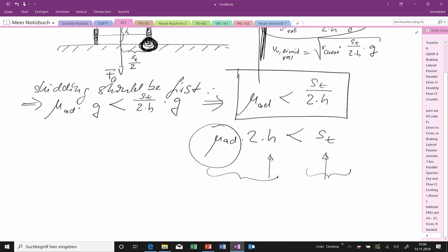So if we steer and we let the vehicle roll to one side, and then we steer in the opposite direction, and it rolls back to the other side, and if we do that excitation with the right frequency, we could meet that oscillation frequency of the vehicle. Again, back to the simple situation, I have a spring and a mass.